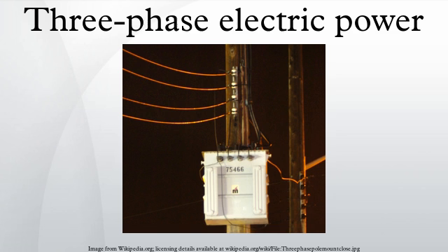Most automotive alternators generate three-phase AC and rectify it to DC with the diode bridge. Transformer connections. A delta-connected transformer winding is connected between phases of a three-phase system. A Y-transformer connects each winding from a phase wire to a common neutral point. In an open delta, or V system, only two sets of transformers are used.